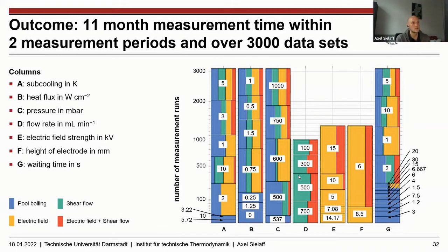A second point was that we also destroyed some heaters in the lab because we put a lot of thermal stress. Building an experiment for ISS was also, just building the heater for us at the institute, quite challenging, because for the foreseen measurement period, which is several months from bringing it to NASA to performing the last measurement, we wanted to be sure that we do not exceed a maximum amount of non-condensable gas.